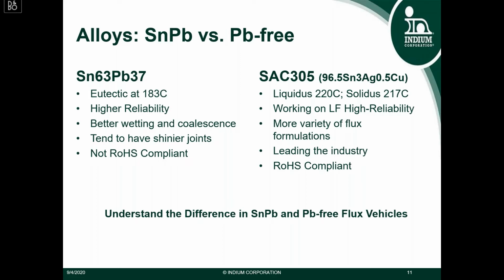SAC305 is not eutectic. It does have a solidus of 217 degrees Celsius and a liquidus of 220 degrees Celsius, giving it a plastic range of 3 degrees. It is a great alloy, however, not as reliable as the tin lead alternative. For this reason, many of us in the industry are working on other lead-free, high reliability alloys.